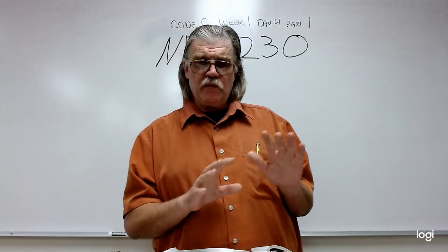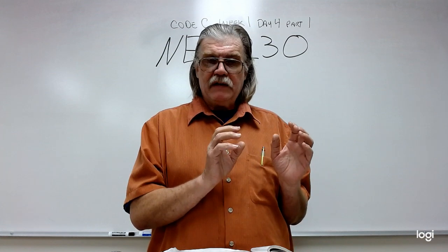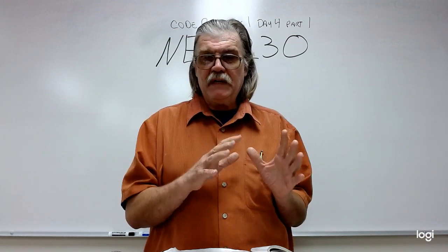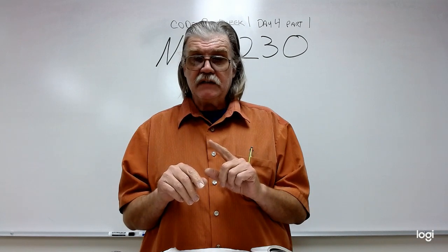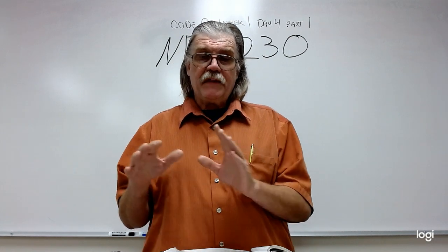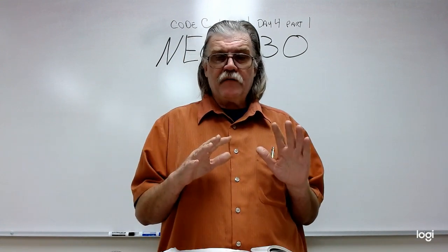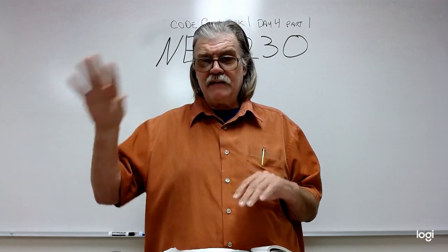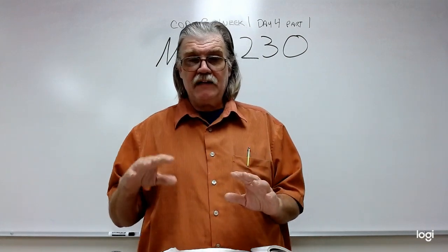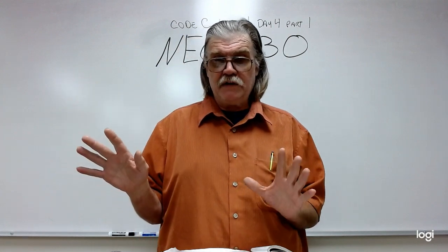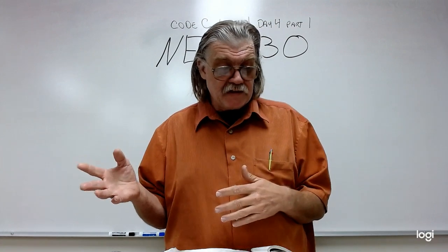So not only can we have these additional disconnects, but we don't want them next to the six disconnects, right? We want them removed a ways from them so the firefighter does not accidentally click them off, or whoever it is that's turning them off does not accidentally click off those vital ones that we just talked about. Fire pumps, right? Or emergency systems, legally required.